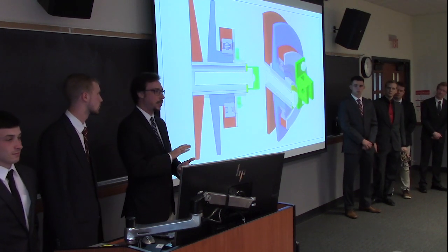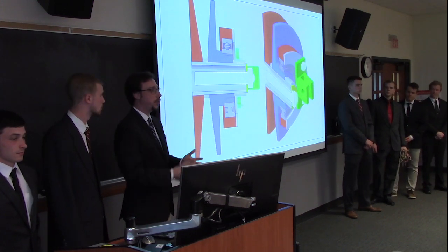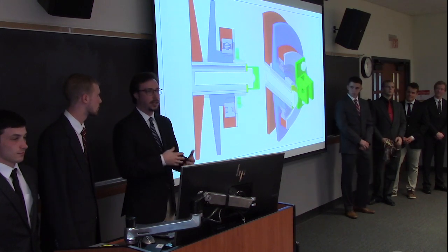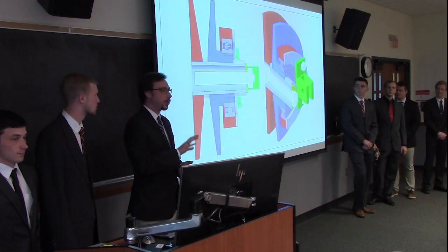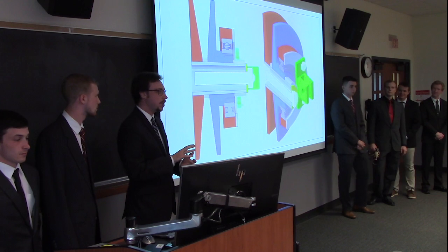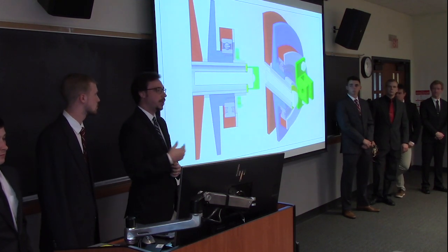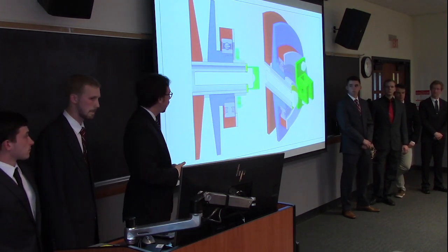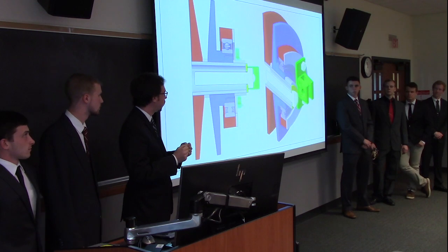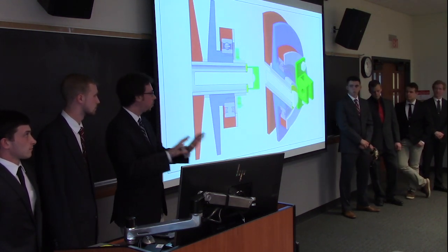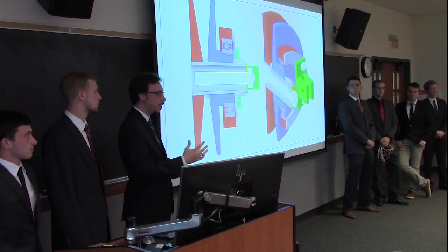This is seated in as a transition fit inside of the housing so as to make service and assembly much easier. But we had to coat the outside of the outer race with an adhesive coating in order to keep it secure. That holds the outer race in place, while the inner race is press fit onto the boss feature of the blue pulley, which will rotate along with the pulley and the shaft at engine speeds. This allows the bearing to be the push and the pull of the system, allowing the linkages to push and pull the housing, the bearing, and the blue pulley along the keyed shaft.